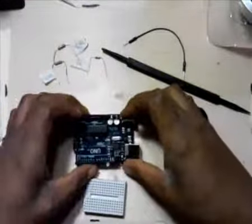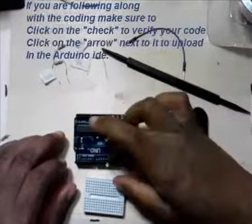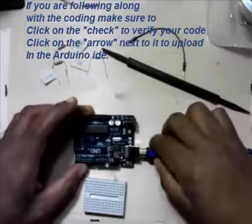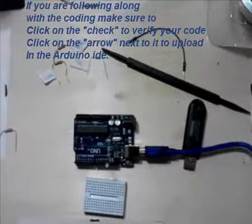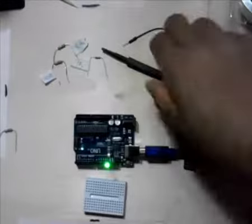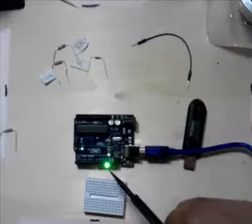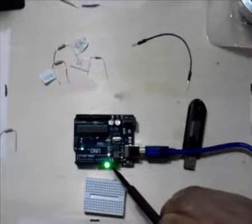I'm hoping that could be seen. Okay, so once we do that, this LED will echo what the on-board LED was doing that was shown before. So when we plug it into the computer, the LED is following along with what the on-board LED is doing. This is the on-board LED. This is the LED that we have plugged with the long lead into pin 13 and the short lead into ground.